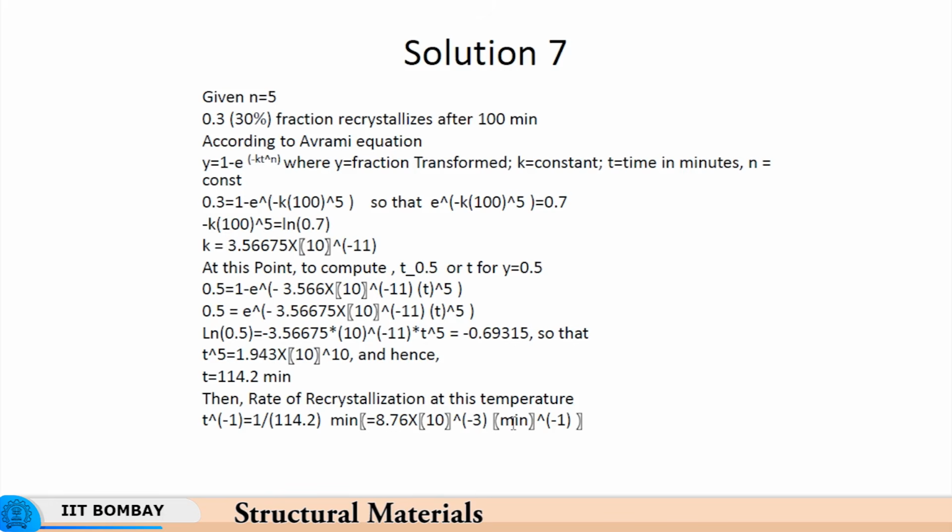So we have a time of 114.2 minutes. So the rate of recrystallization at this temperature is 1 by t, right? And so that is 1 upon 114.2, which is 8.76 into 10 to the power minus 3 per minute. So that is the rate of recrystallization.